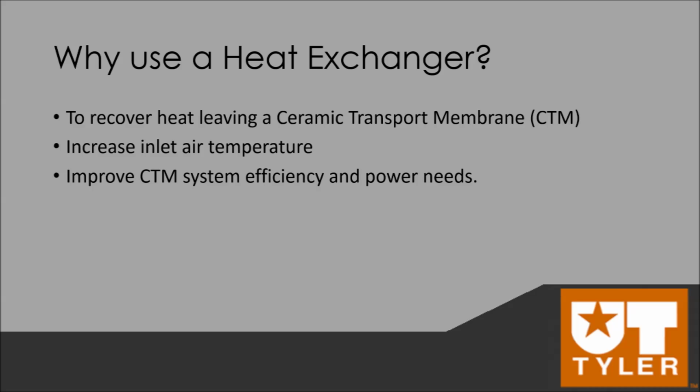The main goal of the heat exchanger is specifically heat exchange from the outlet air from both outlet channels to the incoming atmospheric air at the inlet. The optimization of the heat transfer between the outlet air to the incoming air will result in an increased inlet temperature of the incoming air as it flows through the heat exchanger, gaining heat routed from both outlets. The increased inlet temperature inevitably leads to an overall increase in the efficiency of the CTM system, as less input power is required for the CTM to function as intended.